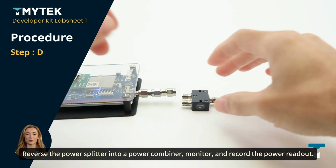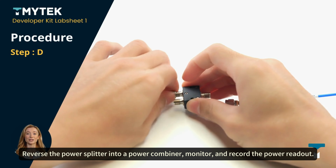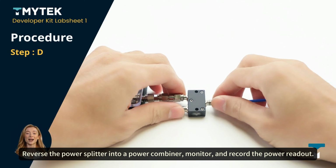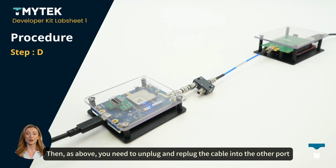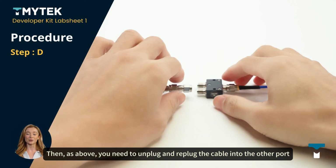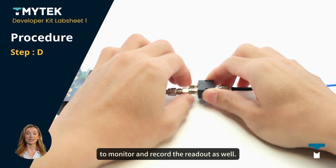Step D. Reverse the power splitter into a power combiner, monitor, and record the power readout. Then, as above, you need to unplug and re-plug the cable into the other port to monitor and record the readout as well.